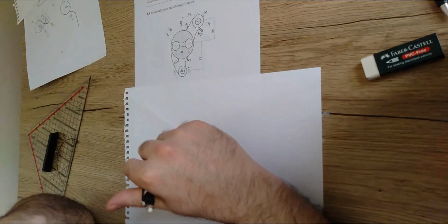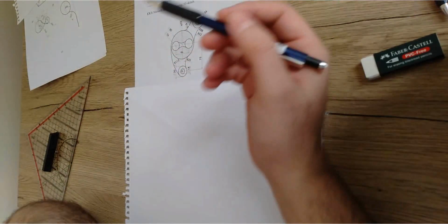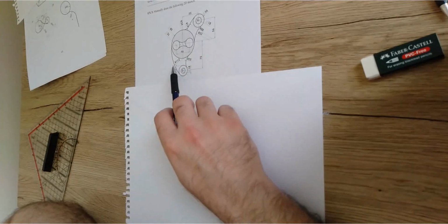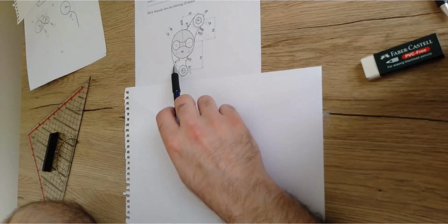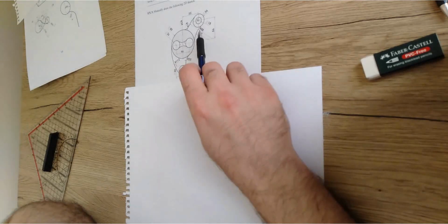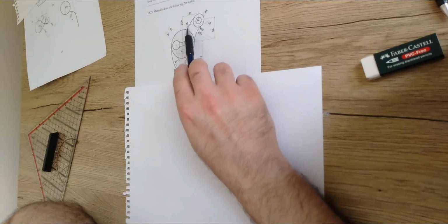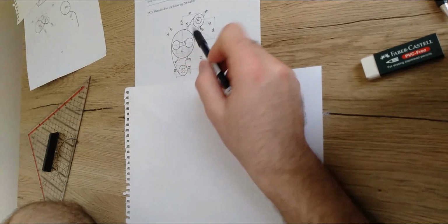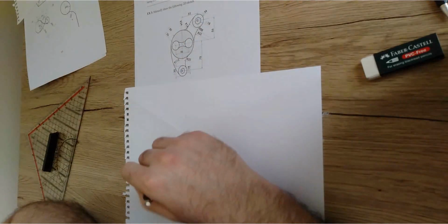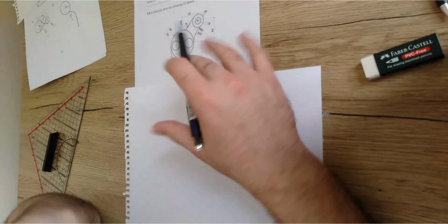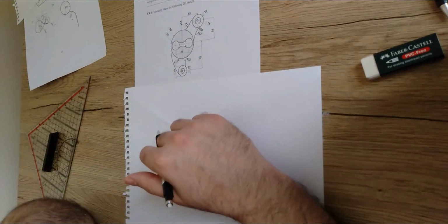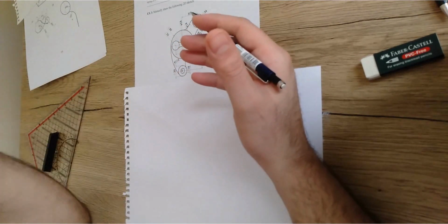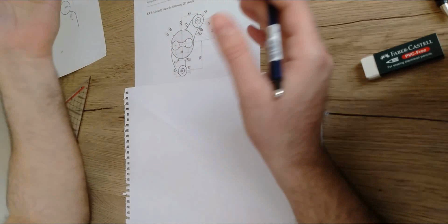the tangencies basically. If we decide to locate these curves, one curve has a radius of 25 and this big curve has a 112 millimeter radius. Also we have this curve and another curve, and there is the 16 curve, which is already this one. So in total, how many tangencies do we have? 1, 2, 3, 4, 5 curves that should be tangent to other objects, circles or whatever, right? So in order to create this drawing, it is advised to keep these curves for the end. The last thing that you're going to do is just these curves.